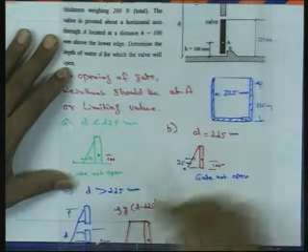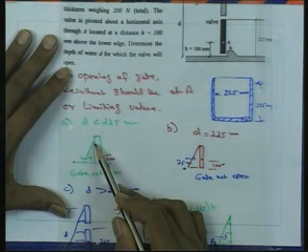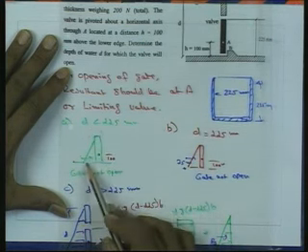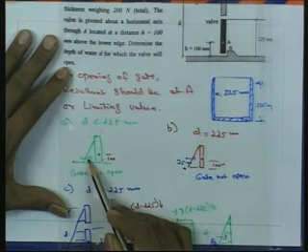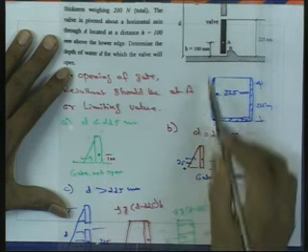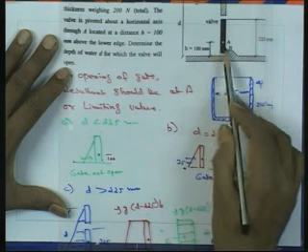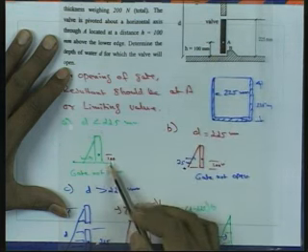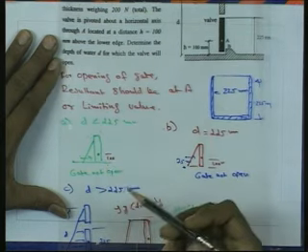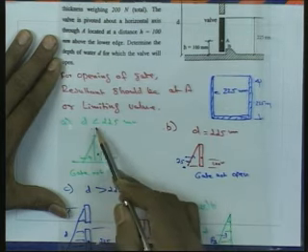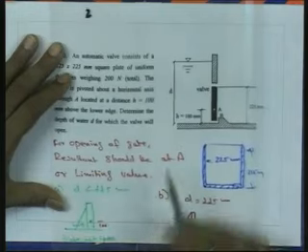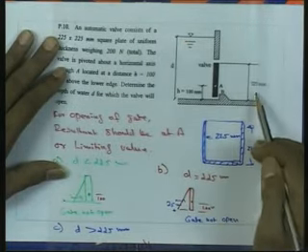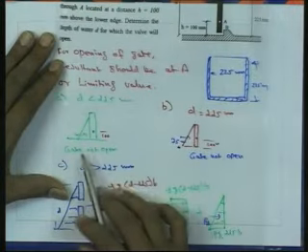So, when I draw the pressure distribution diagram here, you can see this resultant force will act below this 100 millimeter, which is the height of the hinge we are considering. So, when it is less than 100, then you can see that it will not open. So, first case, when D, the depth of the water column on the upstream, is less than the downstream depth of 225 millimeter, the gate will not open.